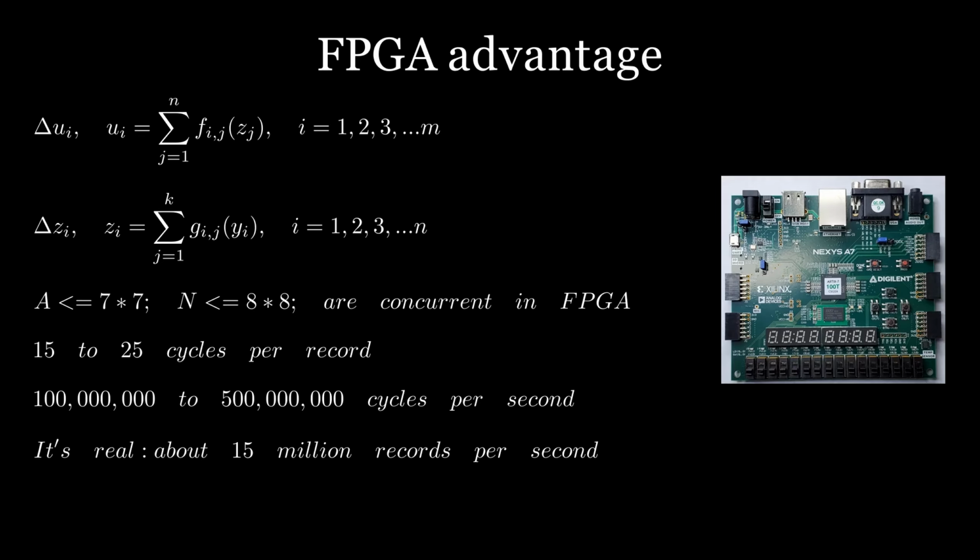The amazing thing about FPGAs is extreme hardware-level parallelism, with thousands of elementary operations executing simultaneously. You describe this parallel behavior using a different style of assignment: no threads, no joins, no synchronization worries. In the third line, you see two assignments executing concurrently. This is called non-blocking assignment, and you can have thousands of them, limited only by the available hardware resources.